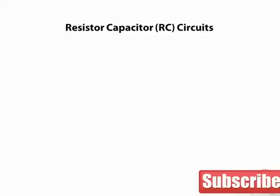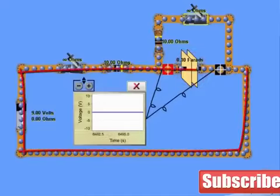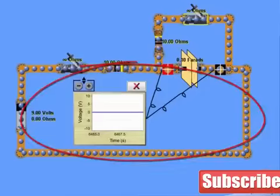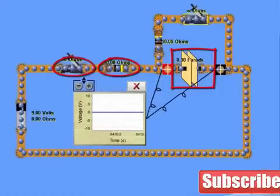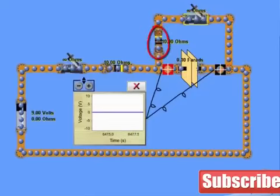Let's build a simple resistor capacitor circuit and illustrate how a capacitor charges and discharges. In this circuit diagram, we have a capacitor hooked up in a couple of different ways. One is a charging circuit and one is a discharging circuit. For the charging circuit, which is the lower loop, we have the capacitor hooked up to a 10 ohm resistor, through a switch, through a 9-volt battery, and then with a return leg back to the other side of the capacitor. The discharging circuit, which is the upper loop, eliminates the battery and is connected to a 10 ohm resistor and a switch, and that to the other side of the capacitor.